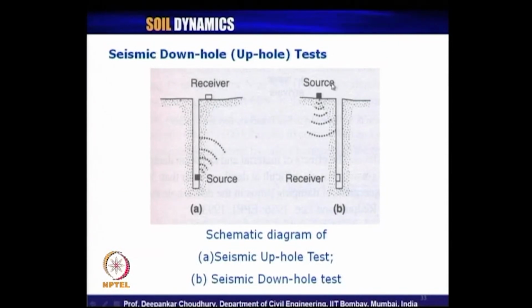And if the positions of source and receivers are vice versa, look at figure B. In that case, the source, where the vibration is created, is located on the ground surface, whereas your recording station or receiver point is located inside the borehole, then it is called seismic downhole test. And then all the methodology is similar to the travel time method.